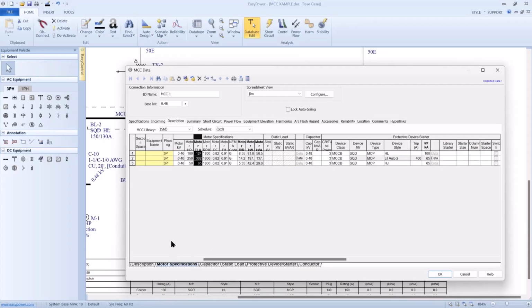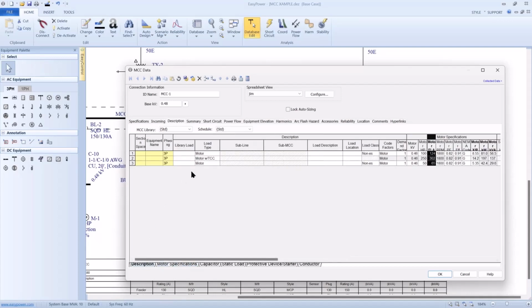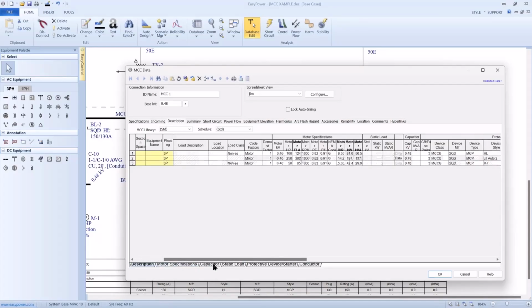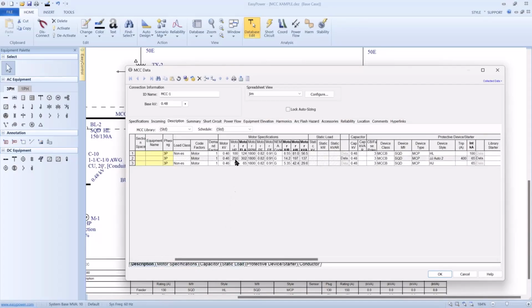So the question from Greg was, Craig, can you still plot a TCC plot? The answer is yes. So it'll plot any load that I have included a TCC with this indication. And that's why you only want to do the largest load. Once I've selected that, when I go to the motor specification for the other loads, we put in the horsepower for that particular load.